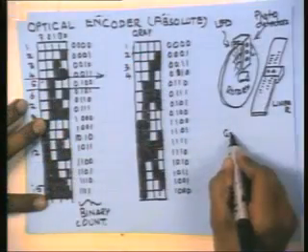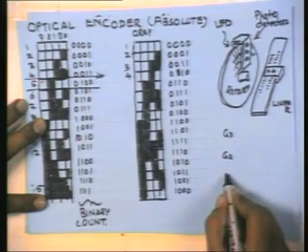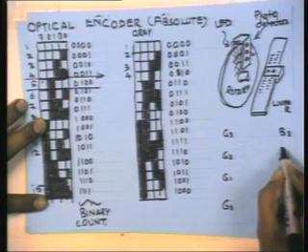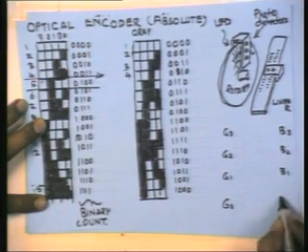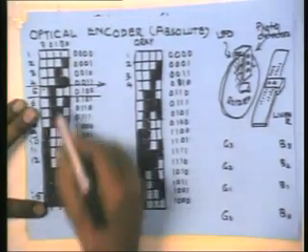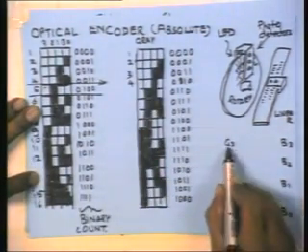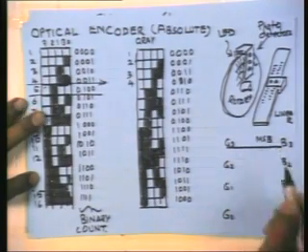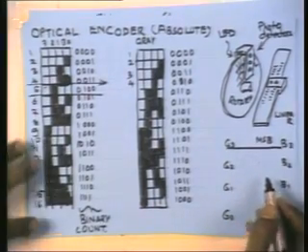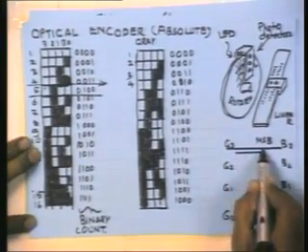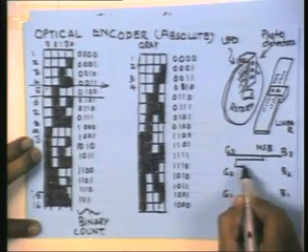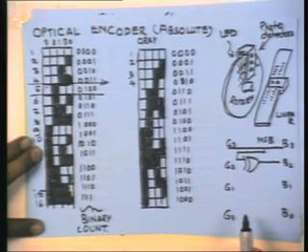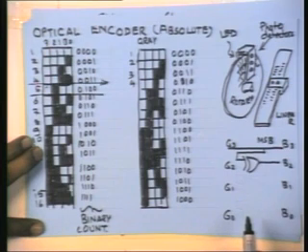You take your gray bit 3, gray bit 2, gray bit 1, and gray bit 0, and here I have binary 3, binary 2, binary 1, and binary 0, and you will notice that there is no difference in the most significant bit. So I connect this together. This is my MSB, or most significant bit. Then for getting the next one, I need to use a XOR gate. So I connect this to an XOR gate and get my B2.